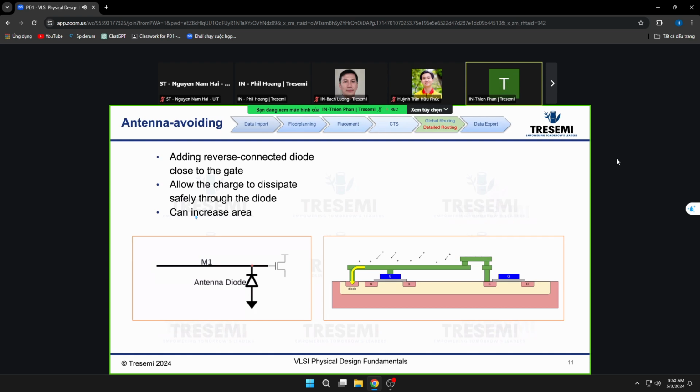You don't want to run through the design, see how many antenna violations come up, and then try to fix them. Every run is slightly different, because you look at the ratio again. Not every single input or pin will have a violation, but the majority of them do.